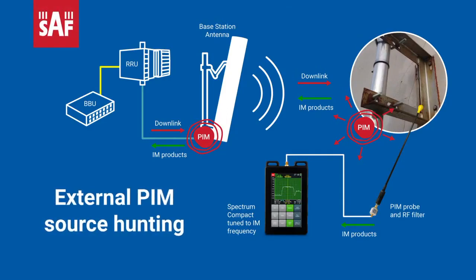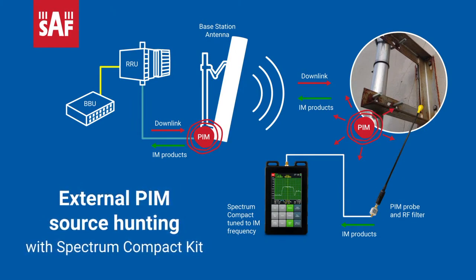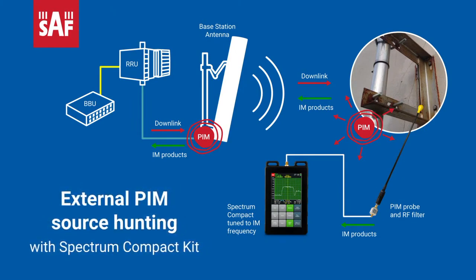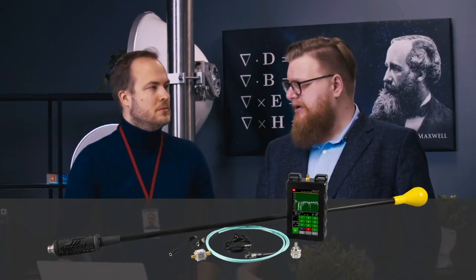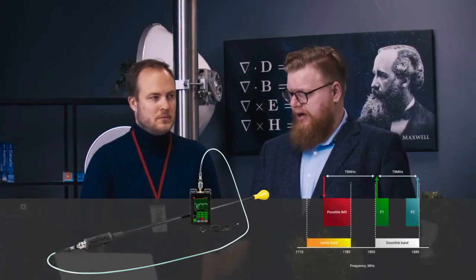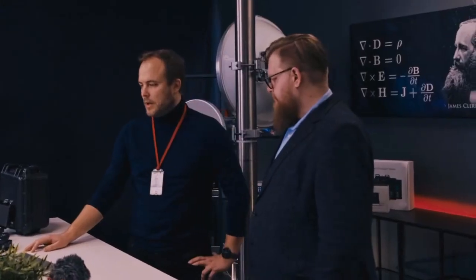or the person installing the site. External PIM is similar, but it would require you to identify the issue the same way with different equipment, obviously. Finding the culprits is a completely different process. You would need to have those two signals being broadcast, the ones that create those passive circuits, while using a spectrum analyzer and a near field probe, and also make sure you're using a filter as well. Then it's as simple as tuning into the frequency that is the culprit, the IM3, and then you literally find the physical location. Just think like a metal detector.